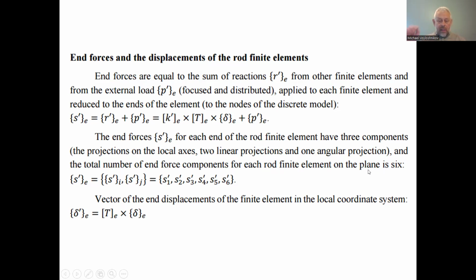So if you consider a flat statically indeterminate frame on the plane, each finite element, that is each rod, has two ends, and each end is characterized by three projections of the end forces.